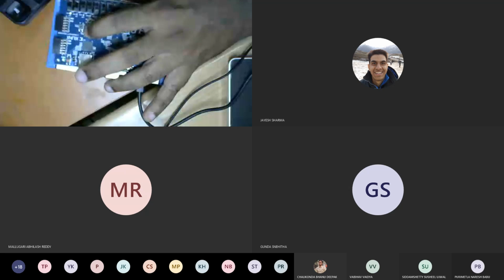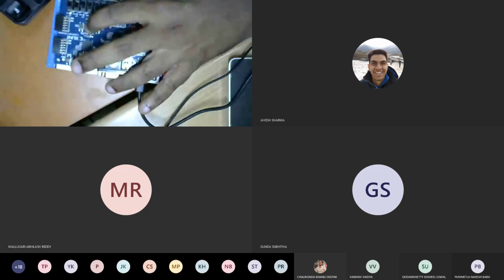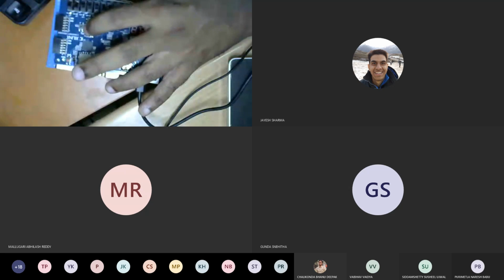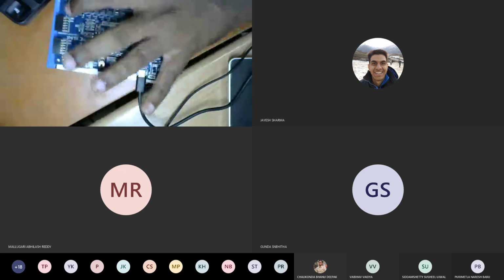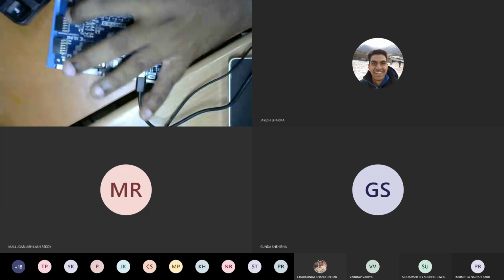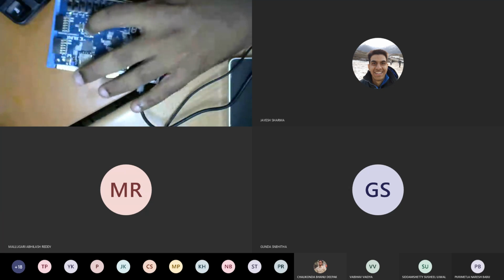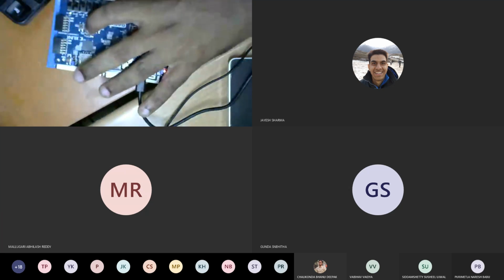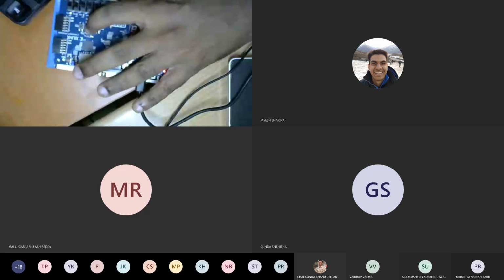I'm pressing still, but I'll release it. Now it doesn't matter how many times I press, because the active clock edge is coming, and at the active clock edge, reset is not active and D equal to 1. Of course Q is always 1. Even if I press so many times, nothing will happen because it's the right value, since D equal to 1.